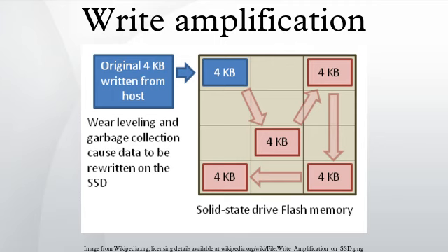Basic SSD operation. Due to the nature of flash memory's operation, data cannot be directly overwritten as it can in a hard disk drive. When data is first written to an SSD, the cells all start in an erased state so data can be written directly using pages at a time in size. The SSD controller on the SSD, which manages the flash memory and interfaces with the host system, uses a logical-to-physical mapping system known as logical block addressing, and that is part of the flash translation layer.